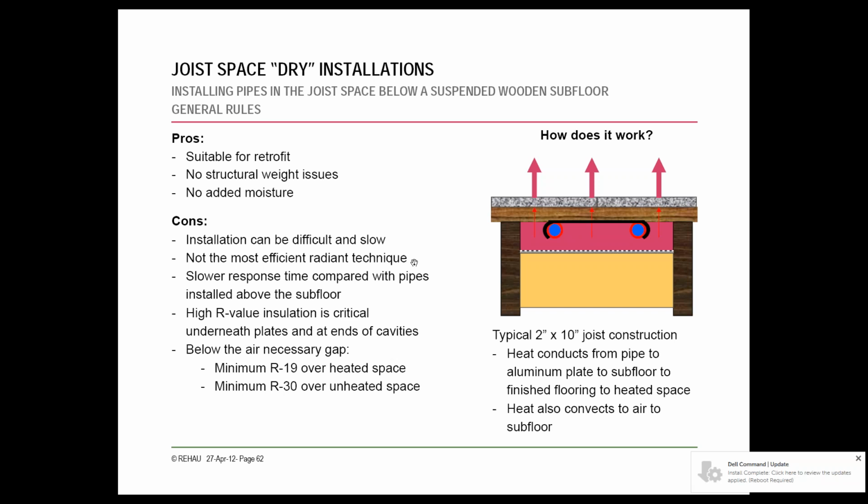The installation can be difficult and slow, but that's really dependent on what all is existing in the joist space below. If you're working around existing piping and whatnot, it can certainly be quite challenging and frustrating. So definitely something to keep in mind.